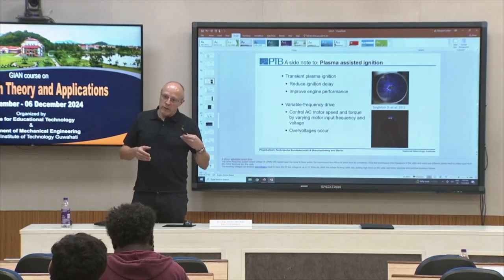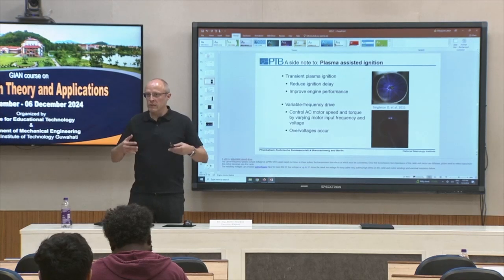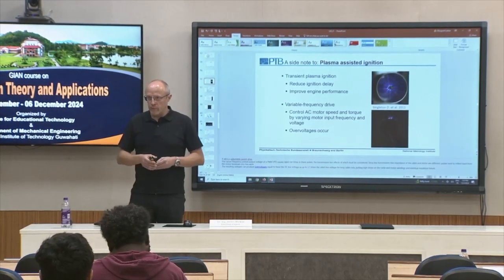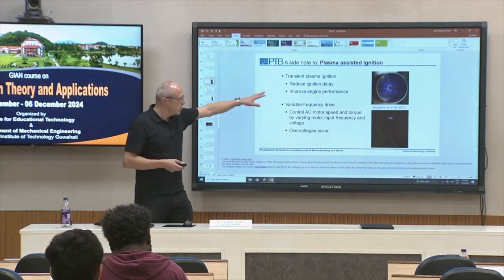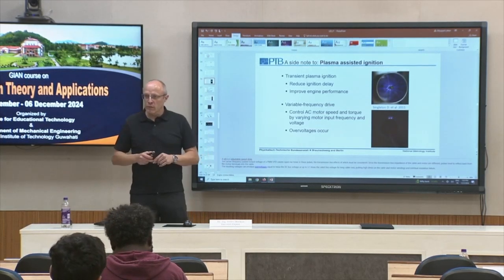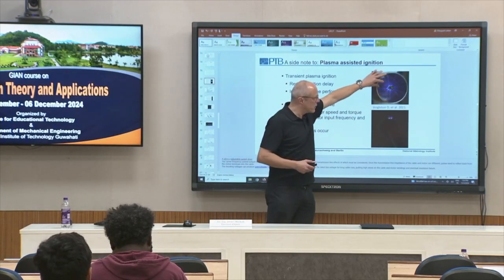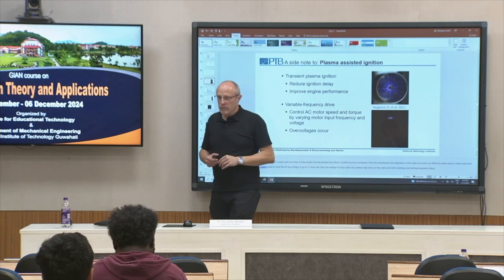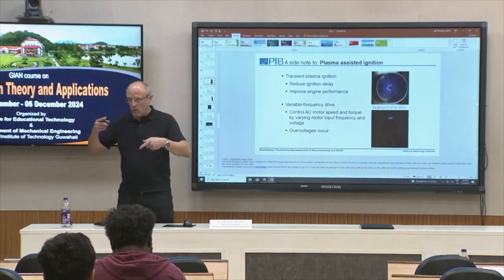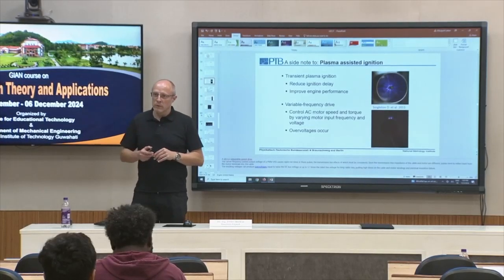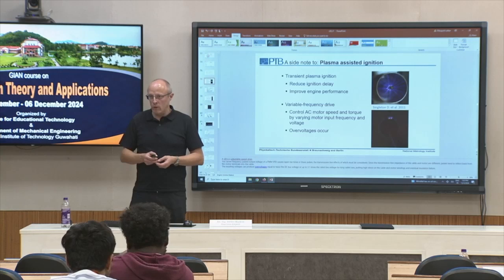So it's more difficult to ignite this mixture. One possibility to get rid of this problem is to use large volume ignition, either using this turbulent hot jet ignition or these non-plasma configurations. So you can reach an ignition in the whole volume. You have faster reaction because there is more consumption per time, and you have a higher probability of having ignition at all.